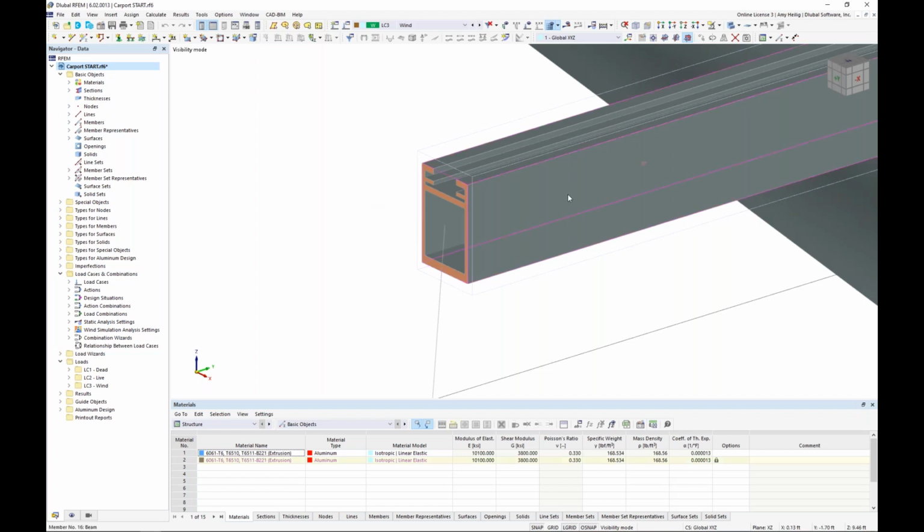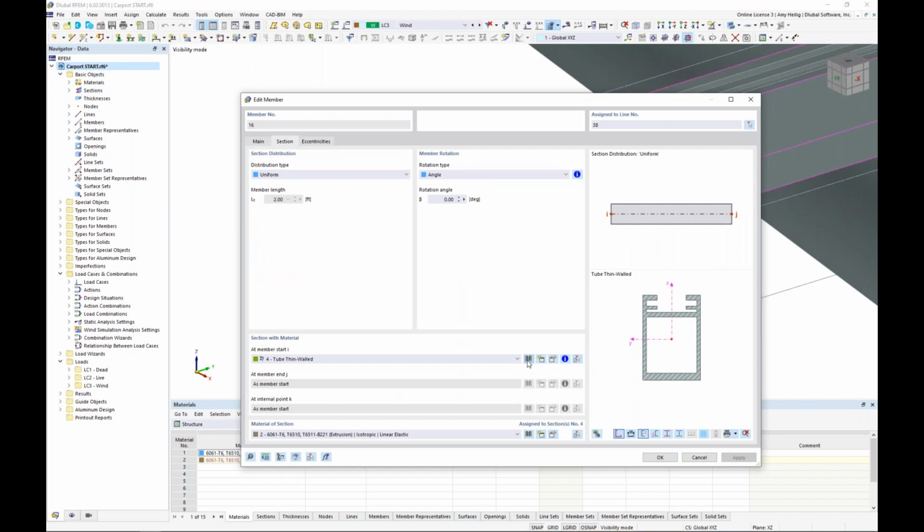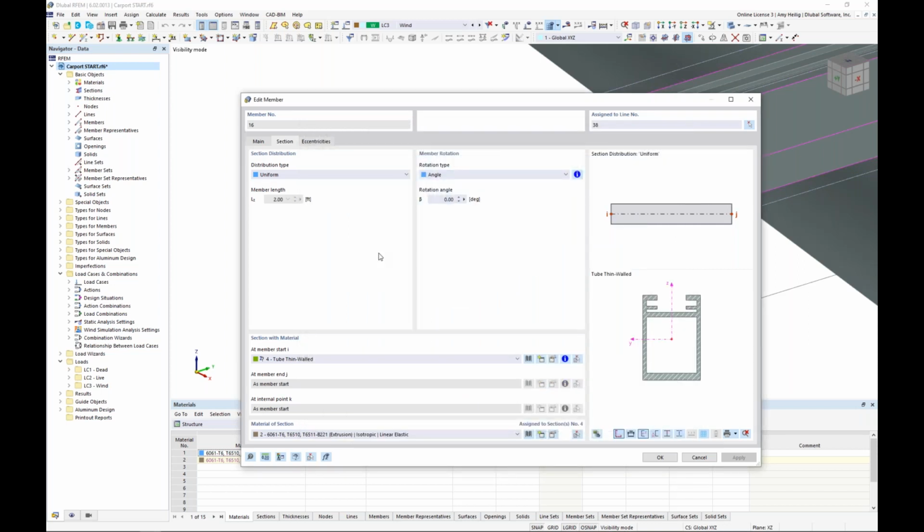And we do so, I'll go ahead and double click on this particular member by selecting a new cross-section from our cross-section library, and over on the right-hand side, we can directly import one of those files. So make sure it has the saved results. We can bring in those cross-section properties, and like I said, even the rendering is there.